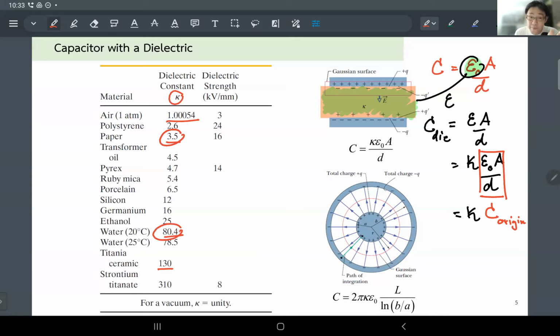If you put water in between, which you shouldn't do in general, you're going to short them out. But anyway, it's possible if you do chemistry, chemical reactions, or photovoltaic stuff, where there are some liquids and you have charged plates left and right. But for us, it probably doesn't make sense to throw water into your blank parallel plate capacitor. That won't be something that you want to do. But anyway, if you want to do it, it will increase your capacitance by 80 times. And now you understand why.